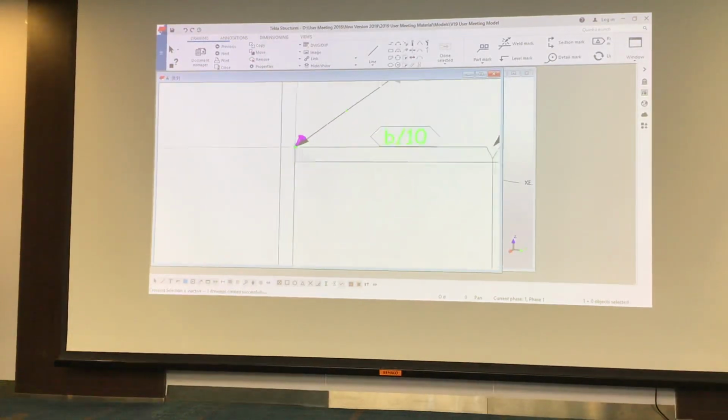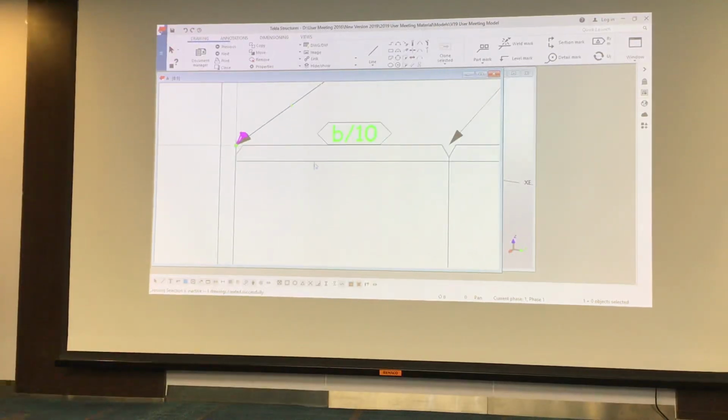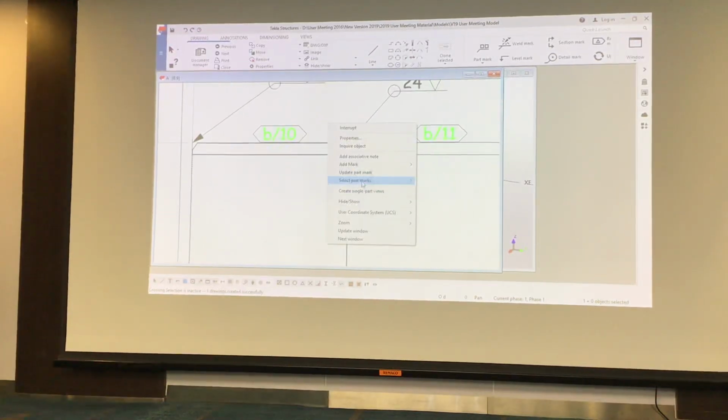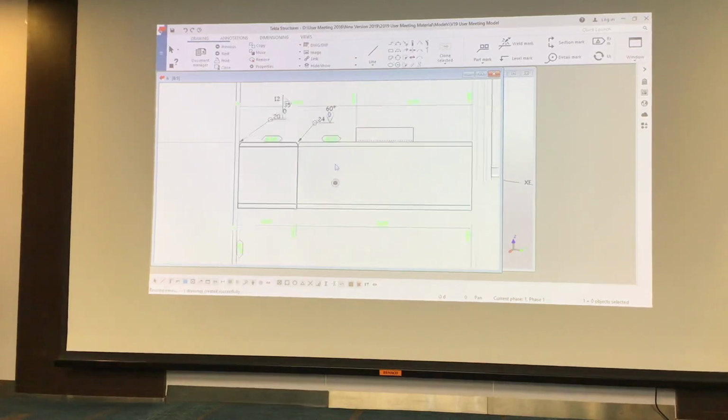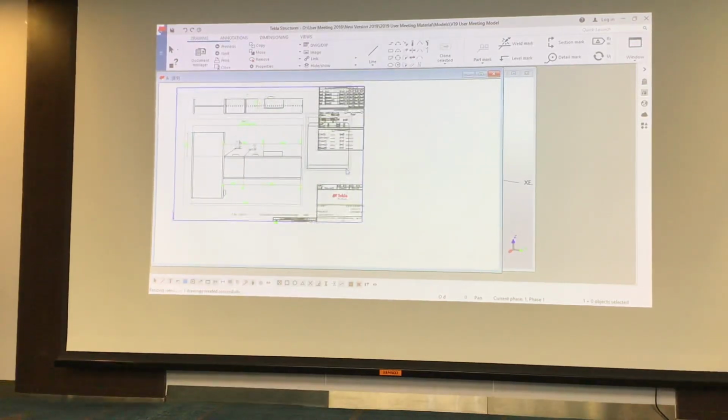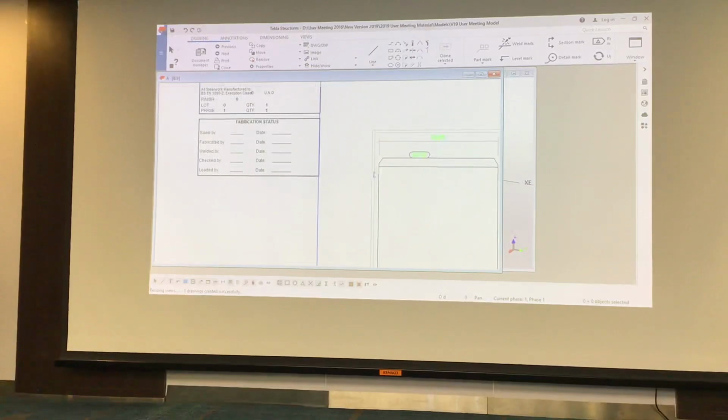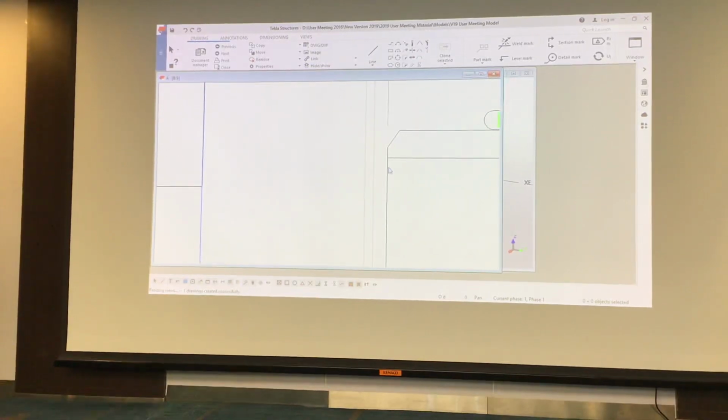The angle, see that the preparations are already there? And if I click on this piece and say, give me a single part view of that, which is here, you can see that piece then has got all weld preparation on it as expected. The weld cuts the piece, so it saves you doing any manual operations.